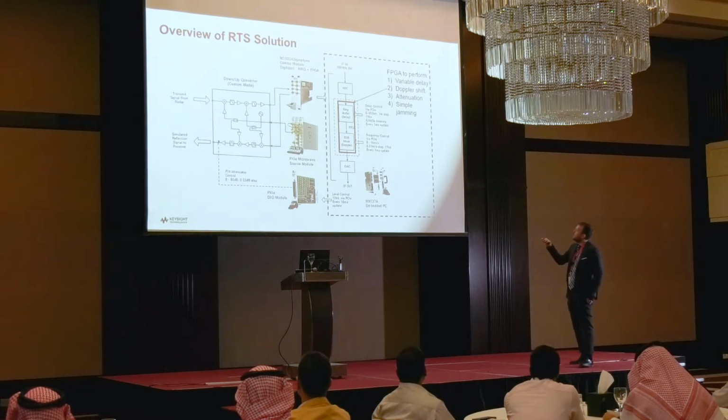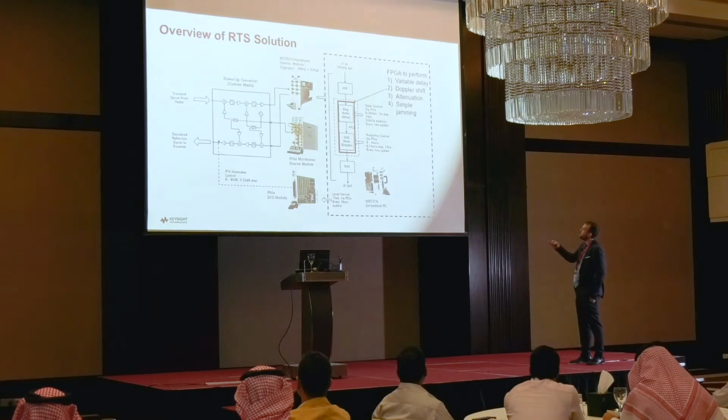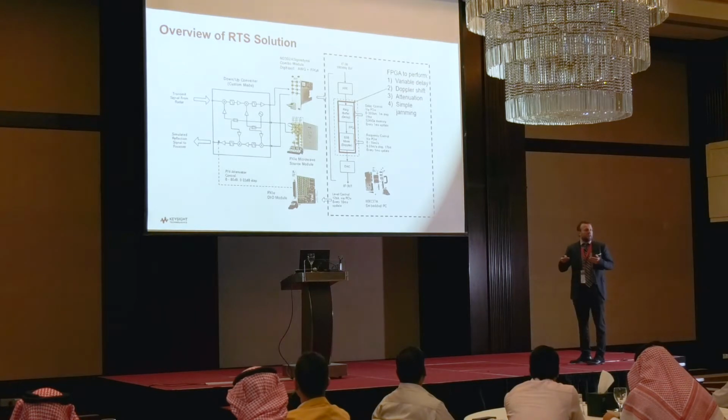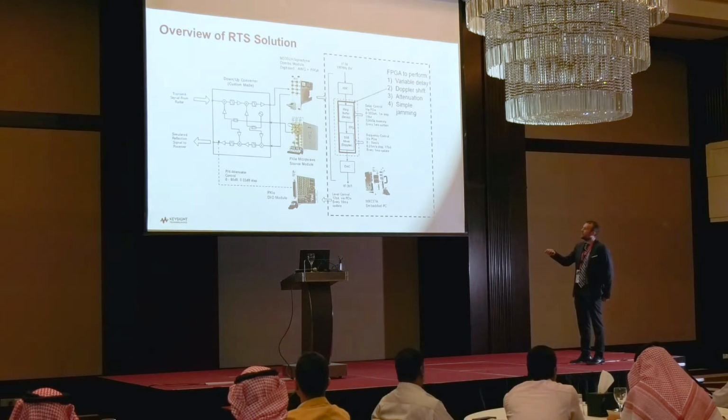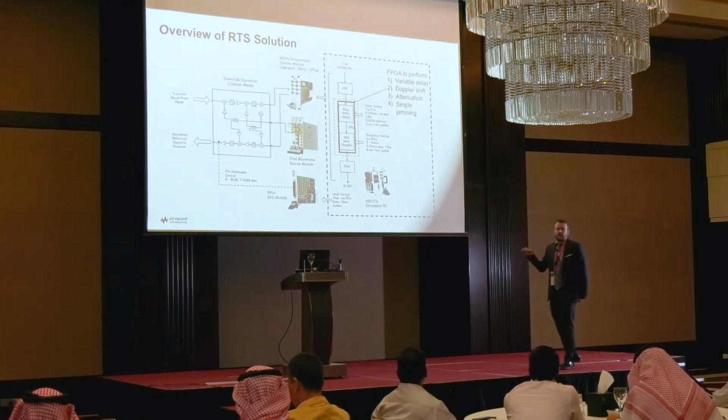Within that, so here we have a zoom into that module. So we have our ADC capturing, we have some processing, and I'll show you the processing afterwards, but basically we can introduce delay, adjustable delay, and an adjustable frequency adjustment to the input signal. And then on the IF, we'll actually generate back out from here, and we can up-convert that and generate our signal. All of this is driven by other PXI modules, so we have a DIO module and a source module that's actually driving our LO for the down conversion and up conversion.